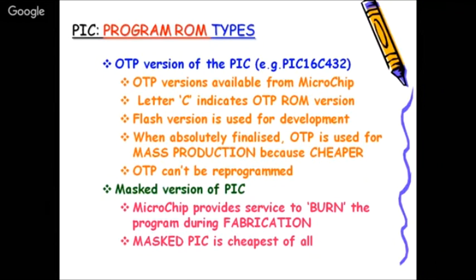दोनों में difference है कि one time programmable है, क्योंकि आपका program आपने final कर लिया using the electrically erasable version. अब आप OTP में एक बार डाल दिया, क्योंकि आप cost optimization कर रहे हो. क्योंकि पहले आपने जब लिया था यही series, let's say PIC 16F 430, C की जगह F था, ये लिया था आपने, तब आपने program final कर लिया, आपका product अब ready हो गया, product को आपने market में launch करना है. अब आप order करोगे PIC 16C वाला दे दीजिए हमें, क्योंकि वो 100 रुपए का cost कर रहा था, ये आपको 50 रुपए में आएगा. ठीक है, the cost difference हो गया. फिर अब आपने इसमें यही program, क्योंकि code दोनों के same है, program करके product में launch कर दिया. Now this you are doing at your end as far as the OTP goes.